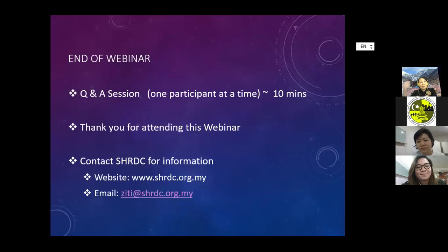And the numbers, this is just a recommendation, and you can find them in class 1, class 2, class 3. So we are expecting that if you do this kind of testing, then your land pattern or pads have to be a higher reliability in terms of this frequent usage and what we call maybe a little bit of extreme environment.